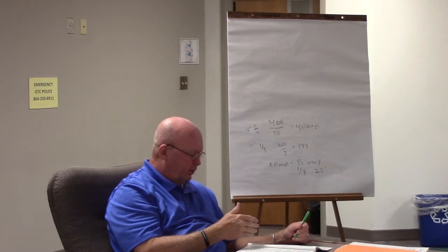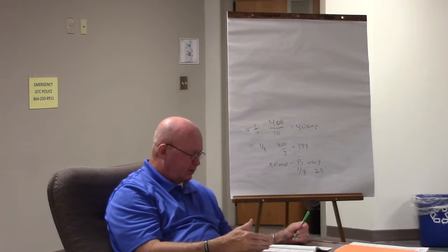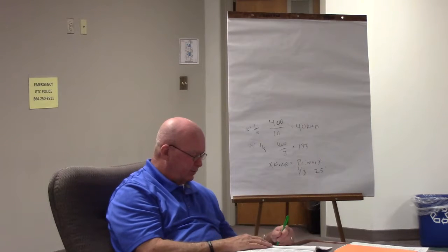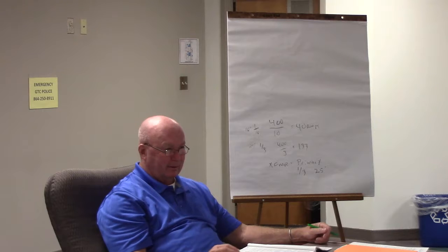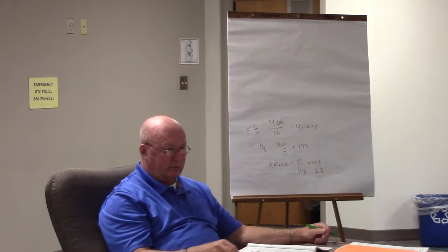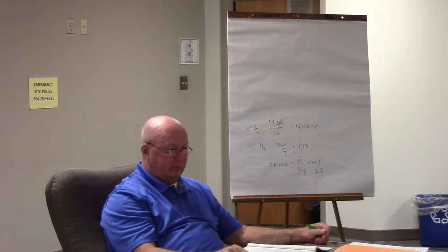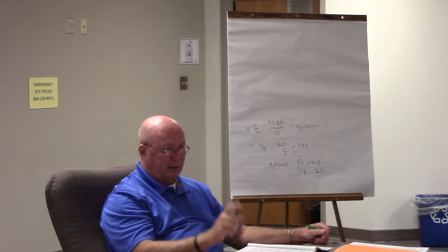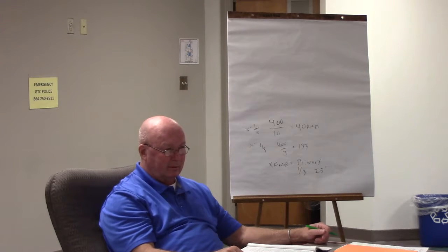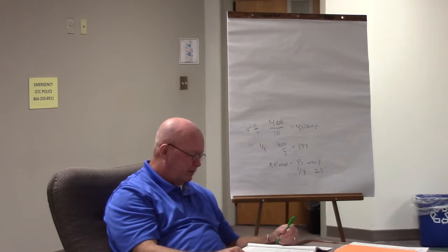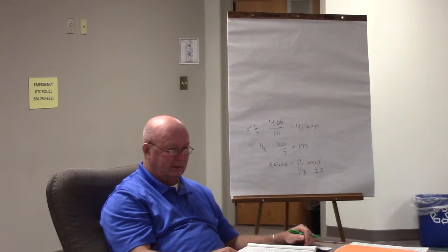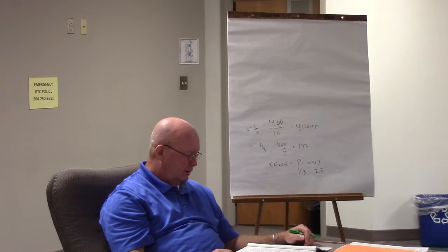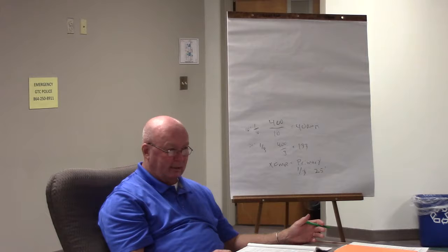Number 4, the disconnecting means is installed in a readily, what is readily accessible location? What does readily accessible mean? You know, cut across or cross facing. Yeah, and you ain't gotta use what? You ain't gotta use tools to get to it, which means what? You wouldn't be using what? A ladder. Okay. Ladder, readily accessible. Is a ladder a tool? I think it is. And if it ain't, I don't wanna be without it, right?